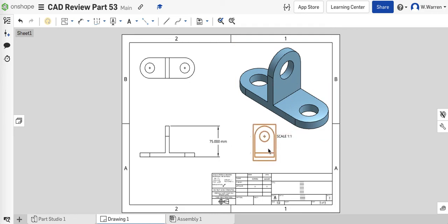But you see now with this little drawing here, I can talk about that whole hole there. So I don't see that hole on either of these sketches. So I can't dimension it if I don't see it. Right, so that's why I had to add this view. Right? Sometimes we have to add another view, and this is one of those cases.